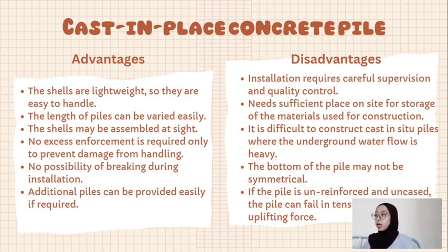Okay, these are the advantages and disadvantages of cast in situ concrete piles. For the advantages, the shells are lightweight, so they can be easily handled. Second, the length of the piles can be varied easily. The shell may be assembled at site, and no reinforcement is required except to prevent damage from being handled. There is no possibility of breaking during installation. And the last one is, additional piles can be provided easily if required.